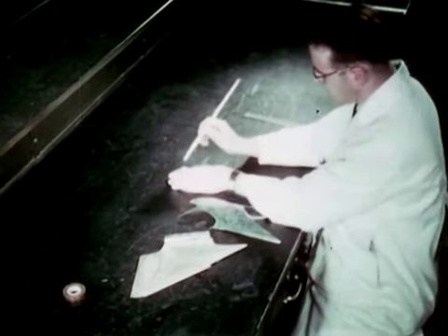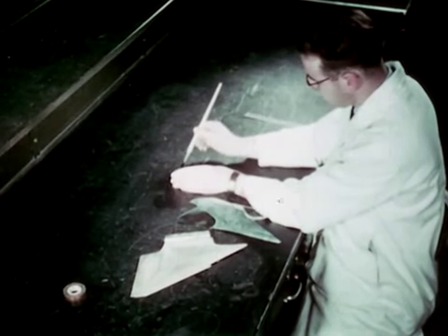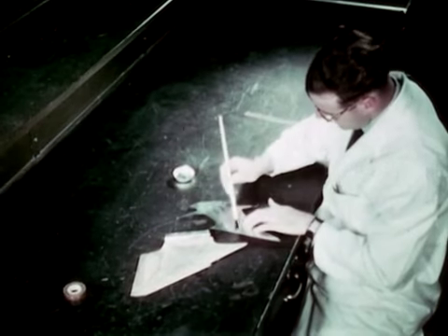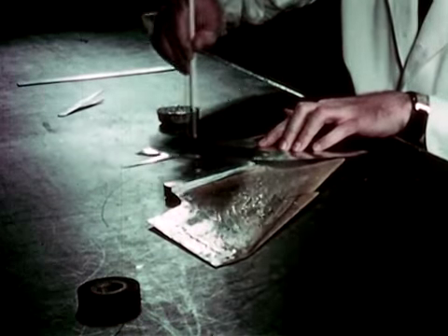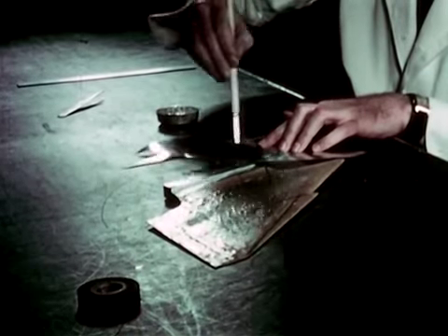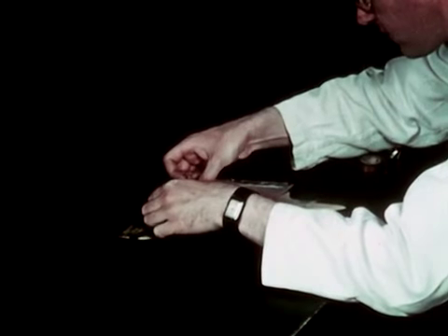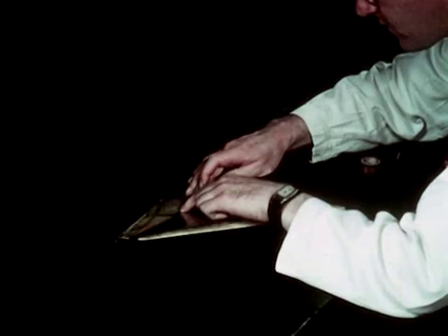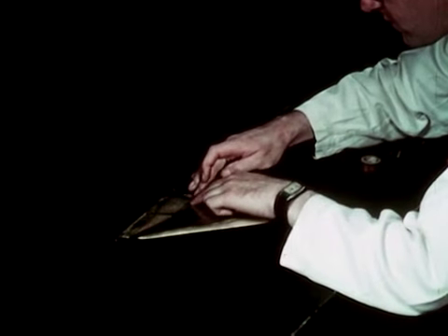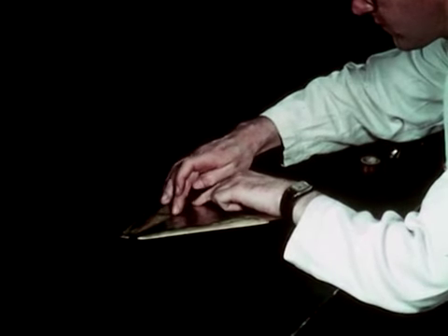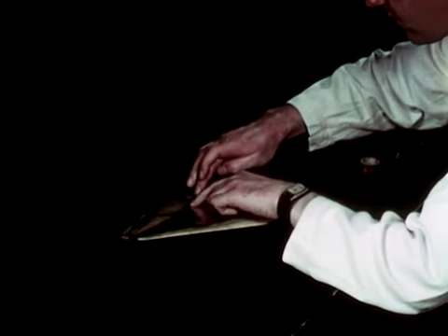The skins were tapered by chemical milling and were bonded to a balsa core. Internal spars and ribs were provided, and balsa leading and trailing edges completed the contour. The models were tested on a vibration table to demonstrate that vibration characteristics were satisfactory.